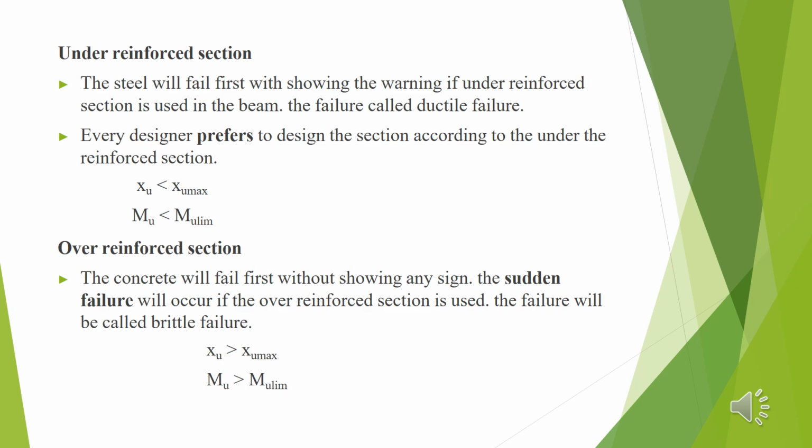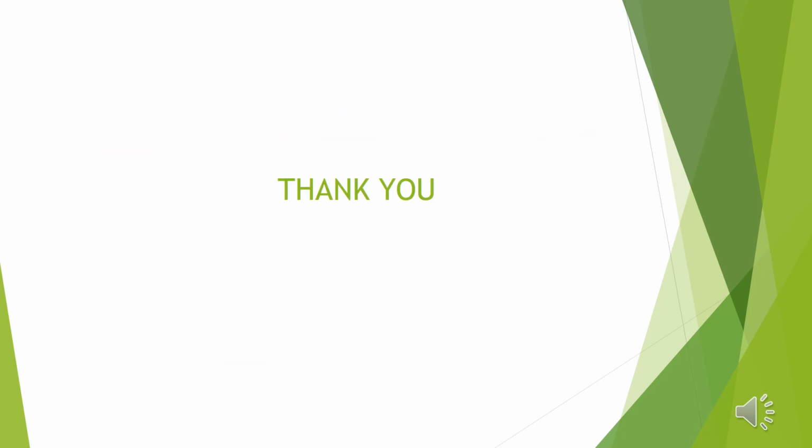It is not preferred, and balanced is also not preferred. We have to go for under reinforced sections alone. In the coming PPTs, we will see about the design of beam members according to our IS 456-2000 in a very detailed manner. Thank you.